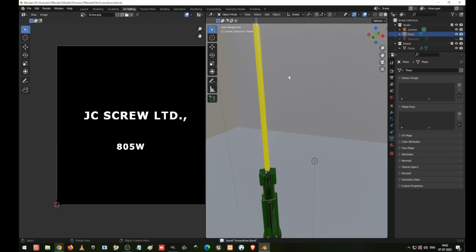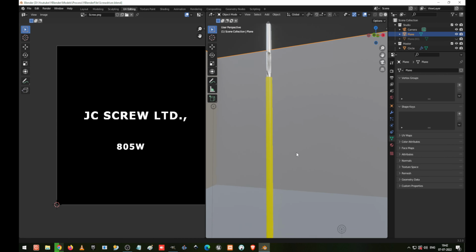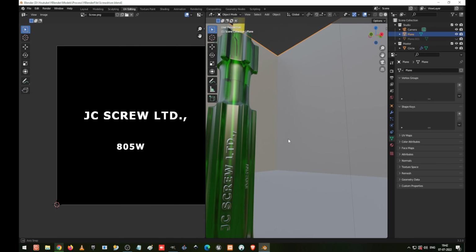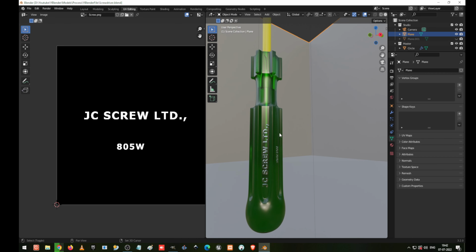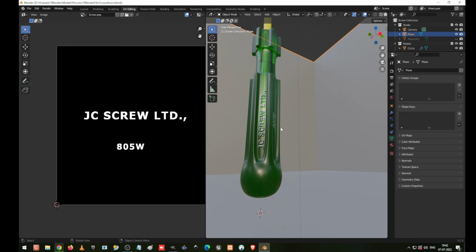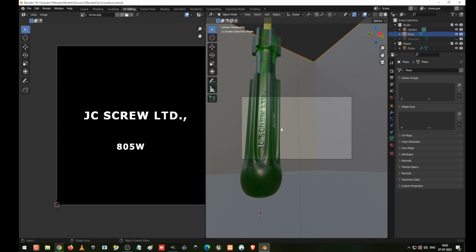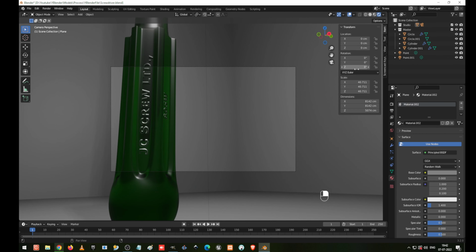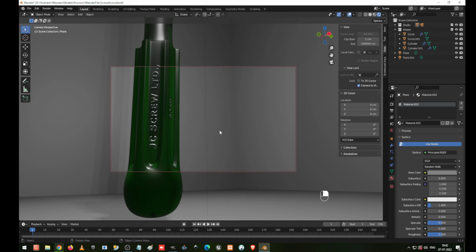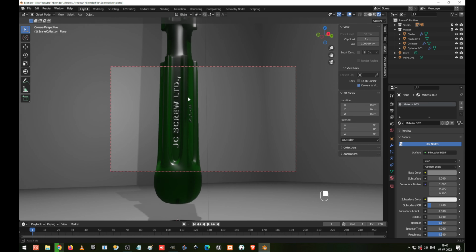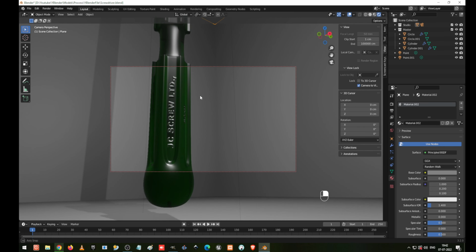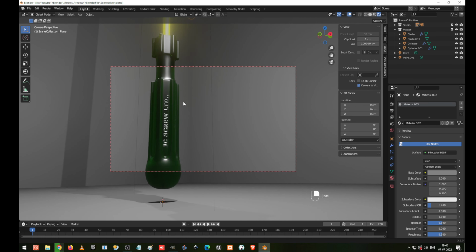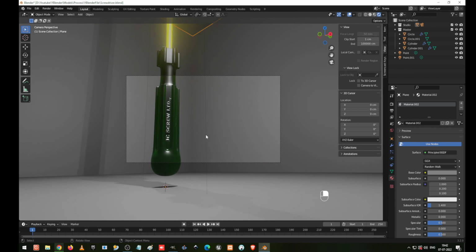So this is the way we design with high modeling and texturing. So I zoom this one. I hope everything has come out correct as per the requirement. Now the screwdriver has been completed. So I press Ctrl Alt 0 to go to the camera angle wherever it's required. I press N on the keyboard and go to the view, and I select the camera to lock, and I select the view which is required for us, and now I turn off this camera view.